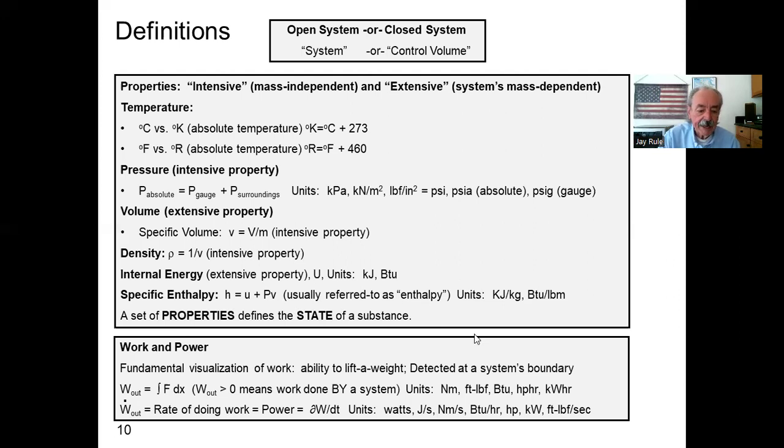Remember, in the second week of class, we talked about the difference between work and power. Let's see, work. Work is the act of moving a force through a distance, the integral of F dx. And in the textbook, you just have capital W. Remember, if you've worked with me, I always write W out. One of my first thermo professors drilled that into our heads. Don't just write W, write W out. Work out is positive. That's work done by a system. If work is done on a system, then W out is a negative number.